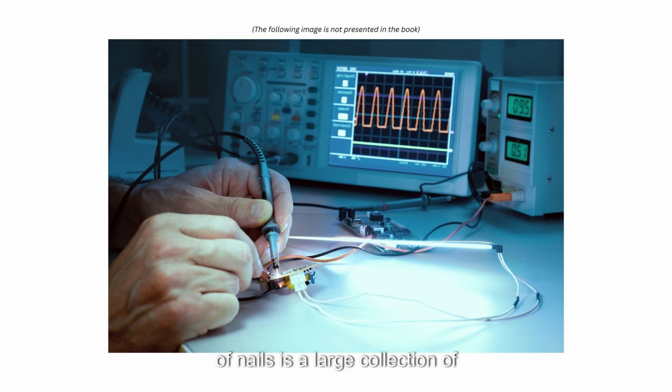A bed of nails is a large collection of spring-loaded probes that are fixed in place. When through-hole components were the standard, a bed of nails test on a 2.54 mm, 100 mil, grid was the arrangement of choice. Even today, the bed of nails test is viable if the PCB is properly designed with sufficient test points to test the PCB functions. Since most boards are now populated with SMDs, and designers need the freedom to place components as necessary to accommodate the board real estate, the flying probe method is more commonly used.